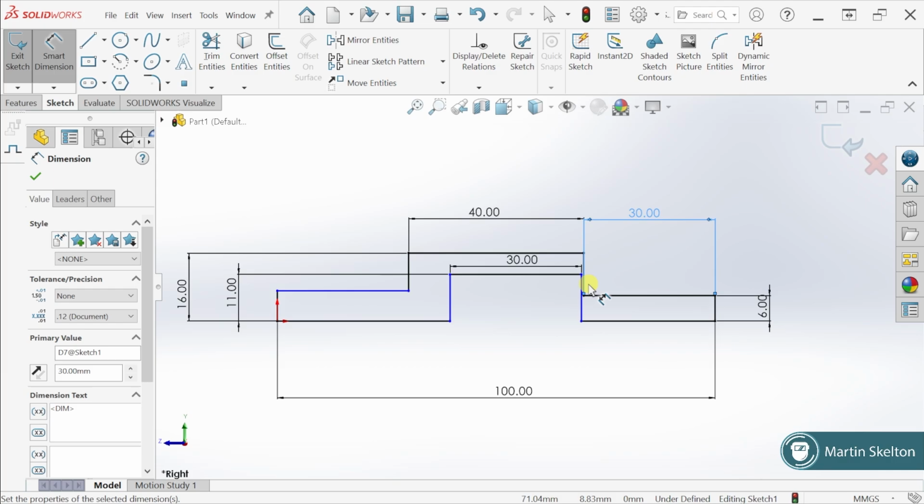But that also creates a problem that if I wanted to create my 40 into a 50, now it's locked in with 5 on either side. It doesn't flow correctly. So how are we going to work on this to make our model react the way we want it to? It has to use more relations. So my relation that I need to put here is that the center of this object, or this line, and the center of this line lines up vertically.